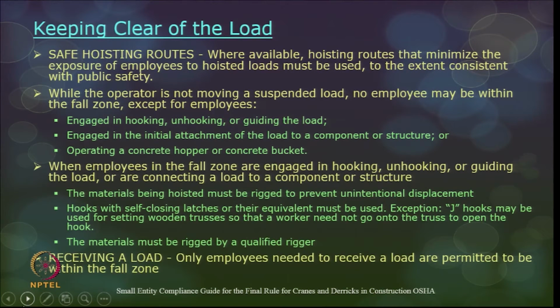Now, keeping clear of the load. As was discussed in several places, whenever heavy equipment or mechanical equipment is used on a site, you have to keep away from the safe moving distance of the equipment. So, you have to keep clear of the load, not standing under a suspended load. All these basic norms have been discussed in several places.